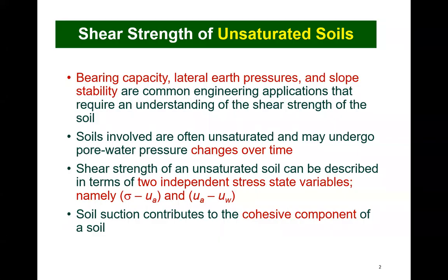There are 3 common engineering applications for shear strength, and these are as follows. Number 1, the bearing capacity of a soil; number 2, lateral earth pressure theory; and thirdly, the stability of natural and man-made earth slopes. Near ground surface, soils above the water table are subjected to negative pore-water pressures or soil suctions. Negative pore-water pressures add strength to the soil.